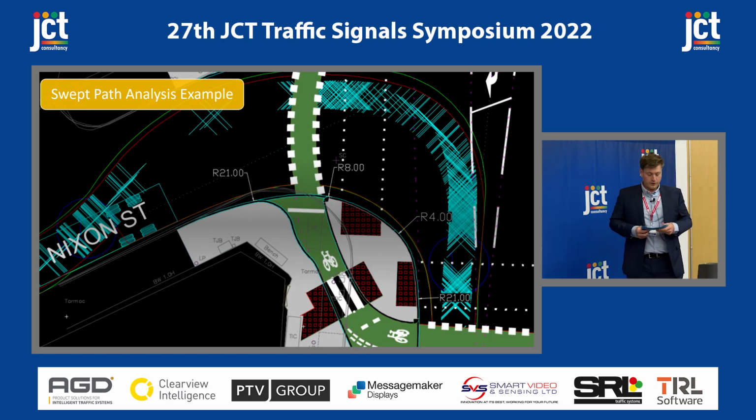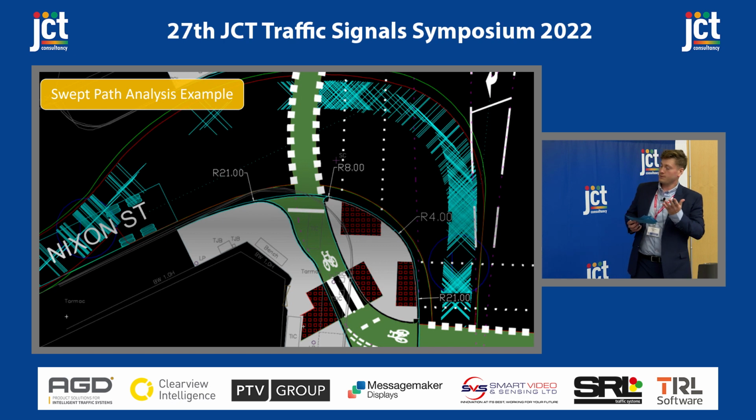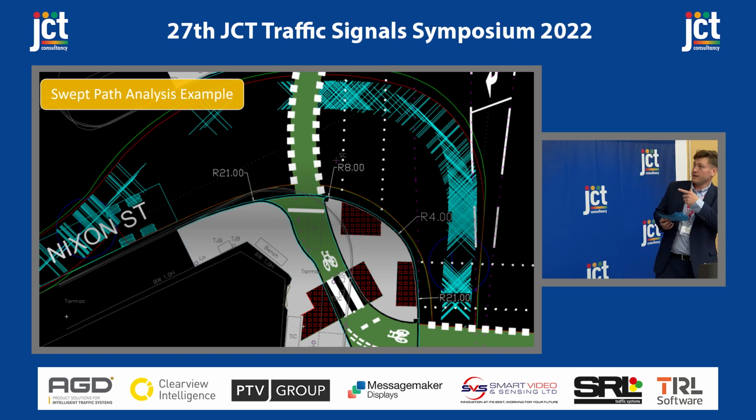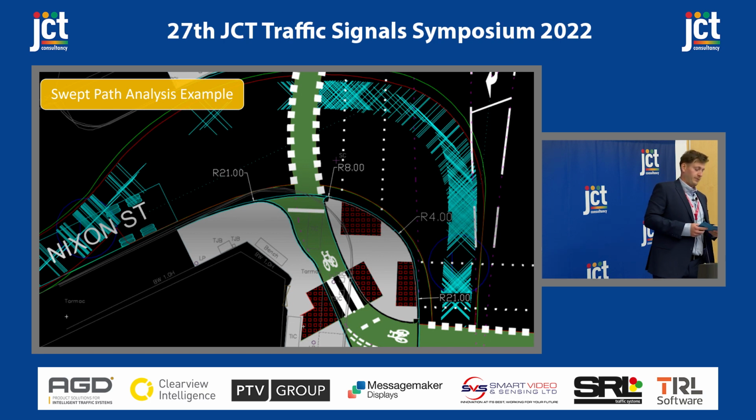So here's another example of compound curve radii to create an optimal solution. So the corner radii here follow the swept path precisely, making sure as much space as possible can be given back to the required walking and cycling facilities, as well as, again, in this instance, ensuring that the right-hand push button can be safely placed and operated easily by its users.